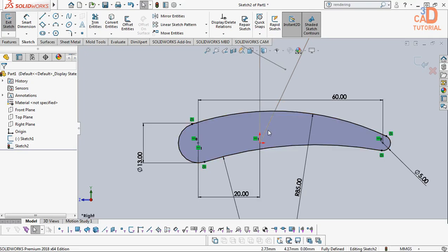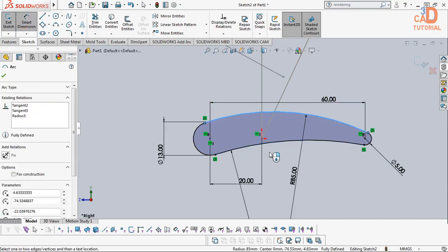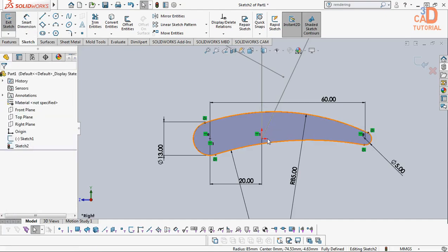Now it is okay, and what is the depth I am getting here? I have to check, because after giving a slot or a cut, it should not affect. How much I have to insert inside this one means maximum I am getting 13 millimeters. If we just insert the mobile inside, nearly 4 millimeters are enough, but we will consider 6 millimeters, and we are moving to the next step.